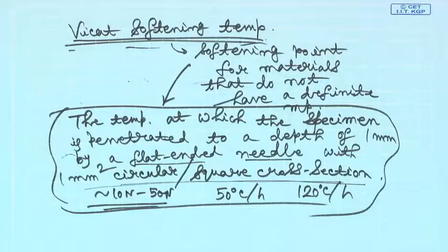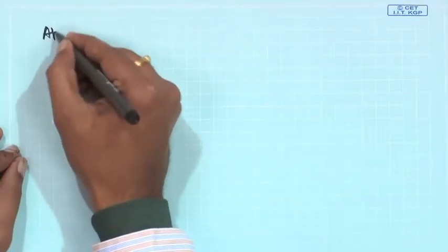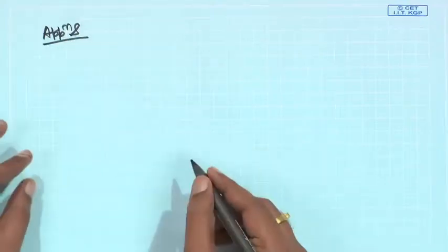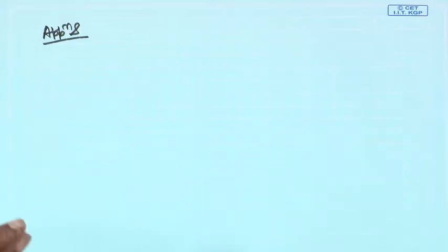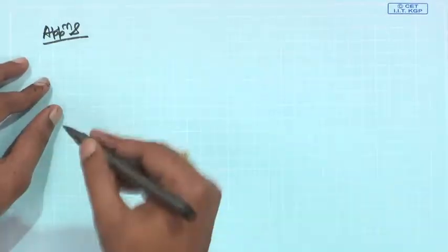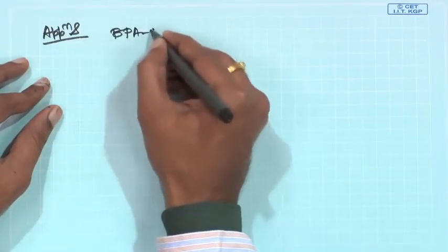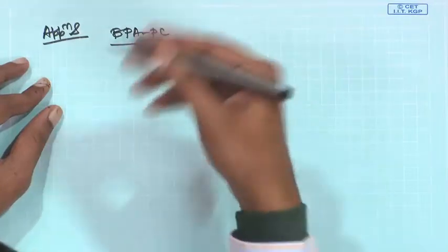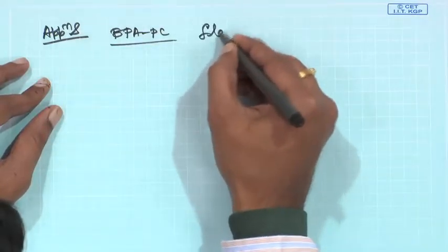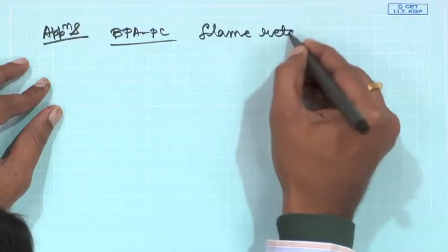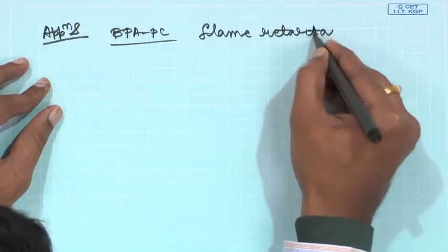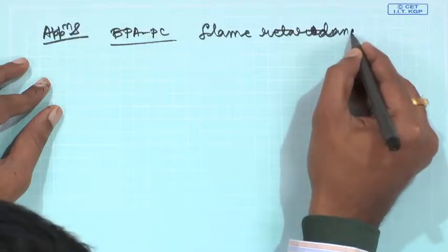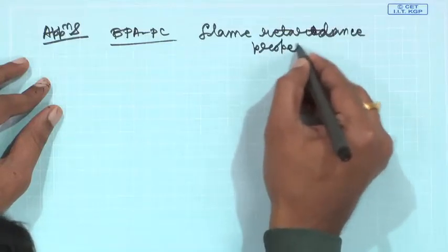Okay. So, basically then the applications of these materials: already you now understand the structure property relations, the intricate details of that, why you need aromatic units, why you need certain substitutions at one position and not in another position, and so on. So, typically BPA, bisphenol A polycarbonates, have outstanding electrical insulation, good flame retardance property, and high heat resistance.